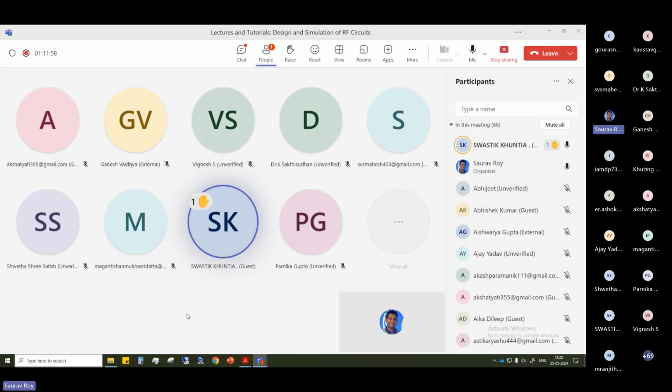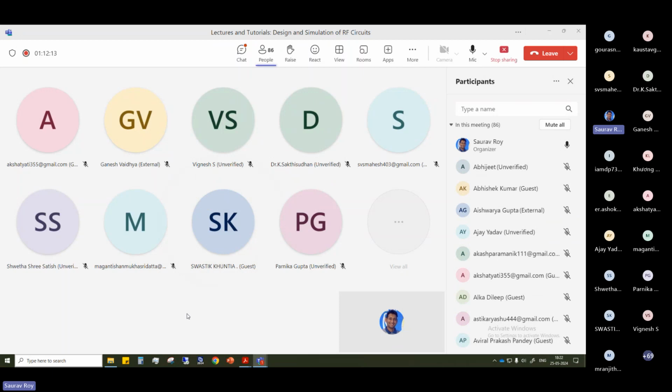See, I don't know if you have done any measurement of a two-port or three-port circuit. Have you done any two-port measurement? Yes, of basic filters and passive components evaluation. Exactly. So if you have to measure a two-port circuit S11 or S22, you have to terminate the other port with a matched impedance load. Usually that is a 50 ohm termination, right? But I do not know whether my filter is perfectly matched or not.